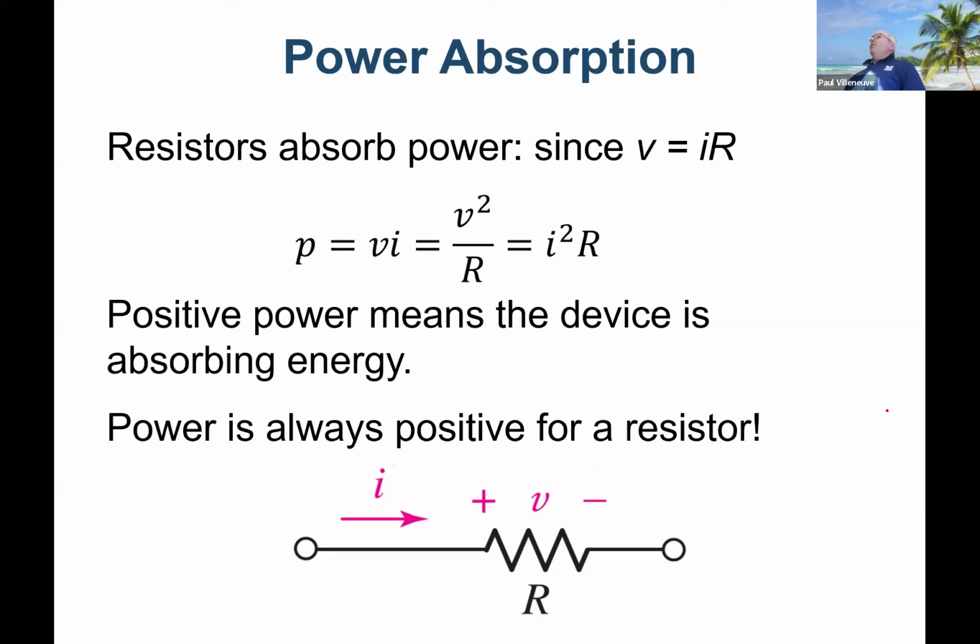One other thing about P, you notice it's lowercase or italicized, depending on your perspective. That's really important because that's called instantaneous power. At any instant in time, it's equal to V times I at those instances in time. So a better way to write this, but I don't because it would get really busy, is V of t times I of t. As long as you have the right time for both the voltage and the current, you can find that value. Because we know in AC circuits, it doesn't work this way, right? It's a lot more complicated. So we have to make sure that we understand that those are instantaneous values.